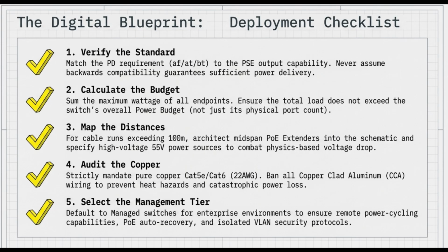In terms of immediate actionable steps, the author should start by implementing progressive disclosure UI elements, like summary boxes and expandable sidebars for those dense electrical specs. Then, they need to rewrite their product mentions, reframing them as applied case studies that solve the theoretical problems just discussed. And lastly, they should build out a dedicated pitfall section, focusing intensely on the mechanics of passive POE burnouts, dual signature negotiation failures, and voltage drop reboot loops.